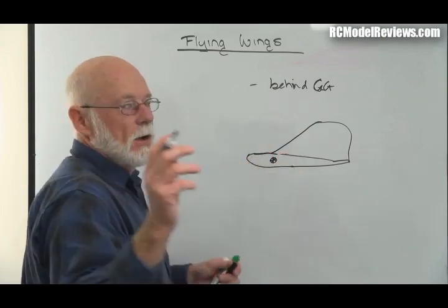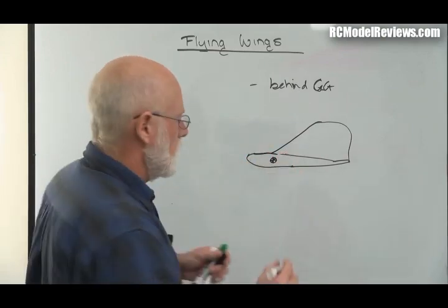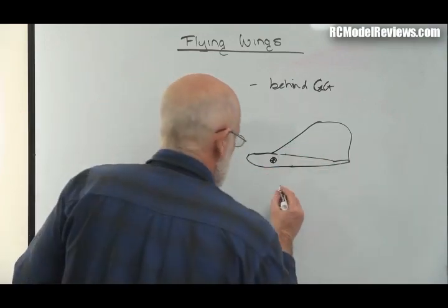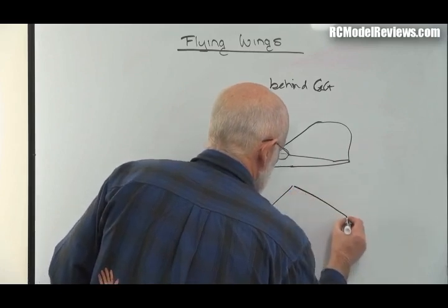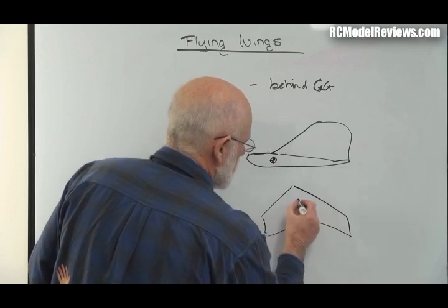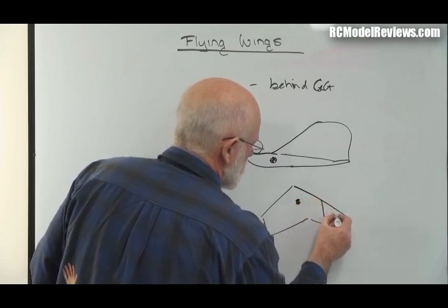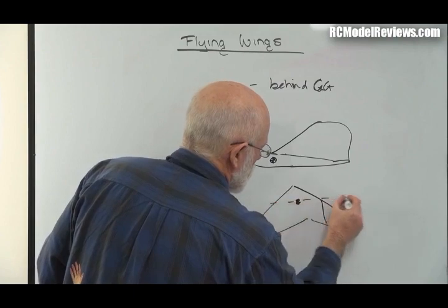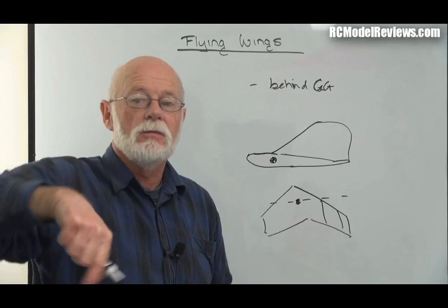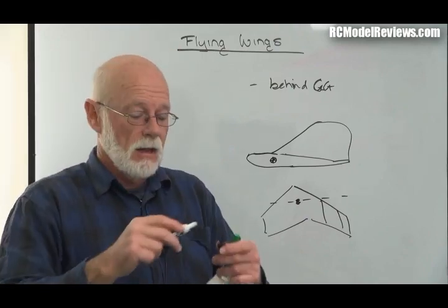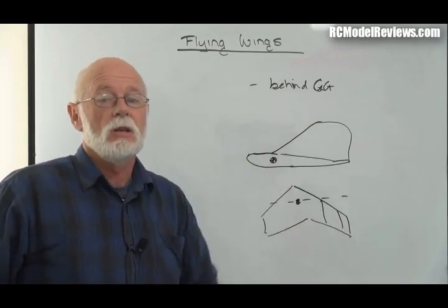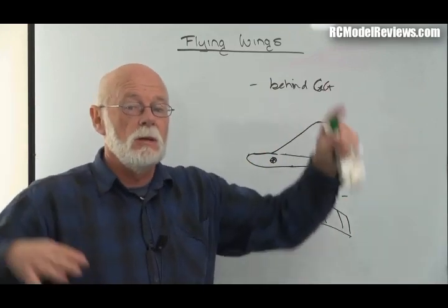That's just working backwards. I've mentioned wing fences, and you notice that I said they could come to the front of the wing, and they should, to stop the span-wise flow. And you can do that with a swept wing, of course, because when you sweep a wing like this, your CG is probably about here, maybe about there. So your wing fences, even though they come to the front of the wing, are still behind the CG. So then you can run them right up to the front. You can run them around the front if you wanted and run them underneath. That'd be the best way to do it, is have wing fences top and bottom of the wing. Stops all that span-wise flow, improves your efficiency, reduces your yaw coupling, stops the wibbly-wobbly.